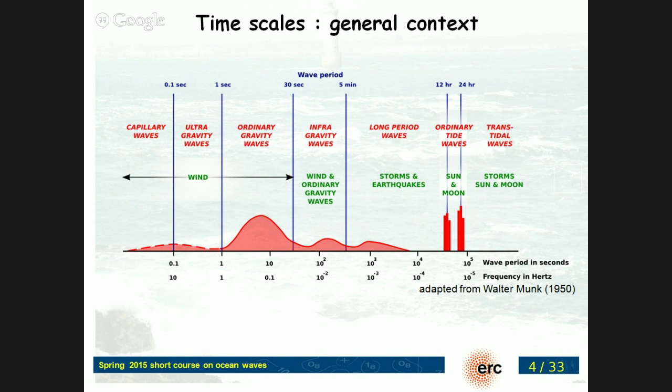Okay. All right. So the short answer is yes, kind of. What you have to realize is that if you want to do everything right, the infragravity waves come from a nonlinear interaction of three waves in shallow water. And in practice, if you want to do it exactly, you need to have the phase, or at least the biphase and the bispectrum, not just the spectrum.